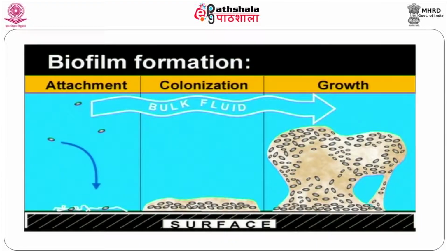If such nutrients are not available in the bulk liquid, these nutrients will be released by the strands and utilized by bacterial species. This is the peculiar advantage of this strand. Another advantage of this polymeric substance is that it will aggregate loose biomass scattered in the liquid phase, and the entire biomass will be adhered on the surface of the solid material. By immobilizing on those solid materials, we may get a growth like this.